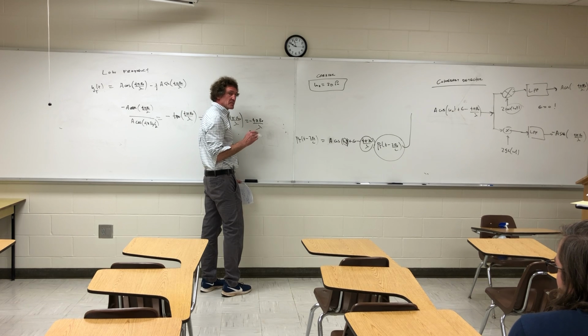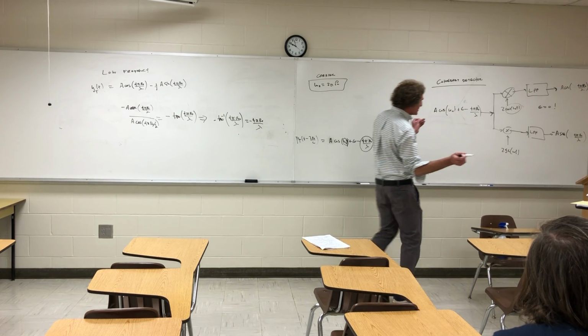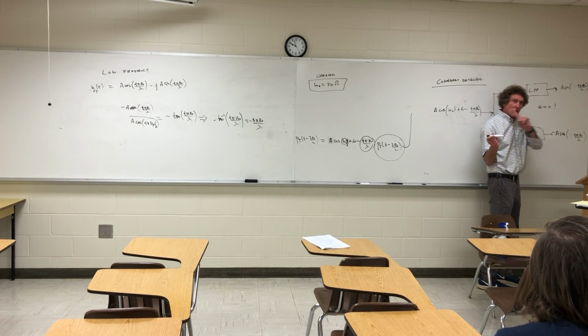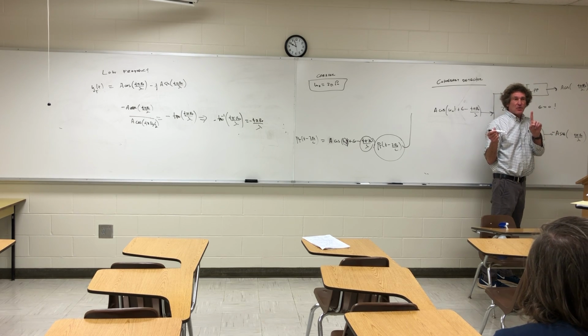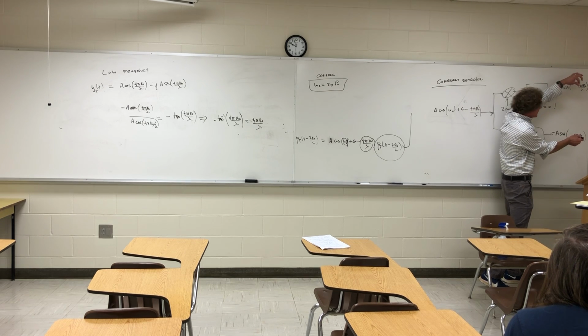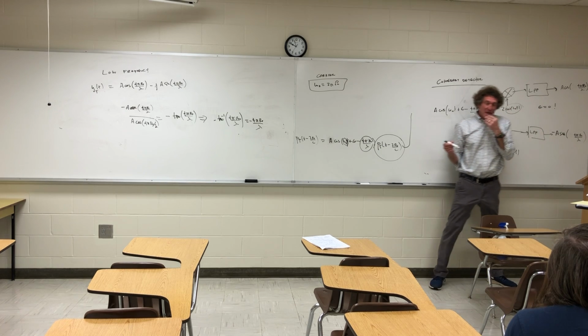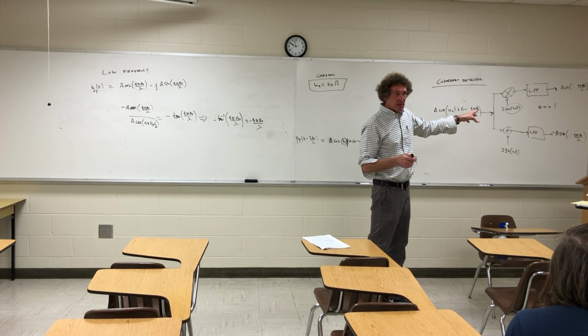And now this becomes very important, something else I didn't say. He doesn't really go into this in the book. What he's really talking about, for one pulse that goes out and back, as it comes back, when we get it at target detection, he samples that simultaneously. Effectively, this is going to be the output of a sampled point. So we get a real and imaginary part because of that J term. Y'all follow me on this one, class?